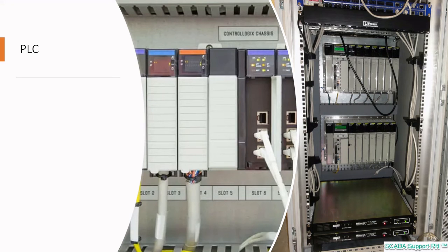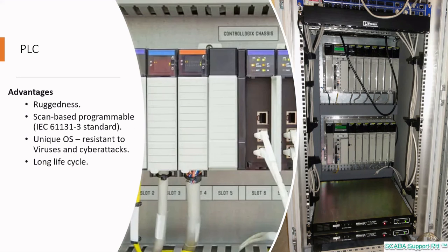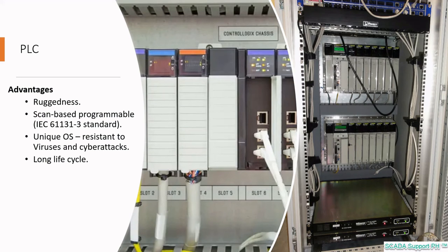A programmable logic controller, or PLC, is a hardware that controls devices or processes based on pre-programmed, closed-loop, or ladder logic. PLC has its own advantages. First off is ruggedness. PLCs are made for reliable operations in very harsh environments. It also offers the ease of programming and troubleshooting, as it usually follows scan-based programmable software.